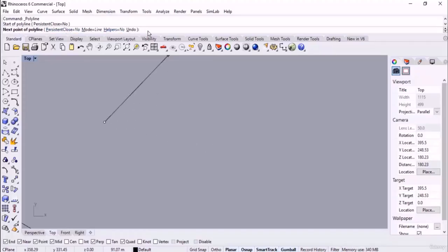I want to attract your attention to the command line. Watch this please. At first, I type the less symbol, and then I specify the degree or angle, 30 degrees for example. But note that when we specify the angle or the degree, for example 30, that 30 degrees angle is not given to us. Right now, the specified angle at which the movement of the cursor is restricted is 30. As you can see, when we rotate it, we got many parts that each of them are 30 degrees.